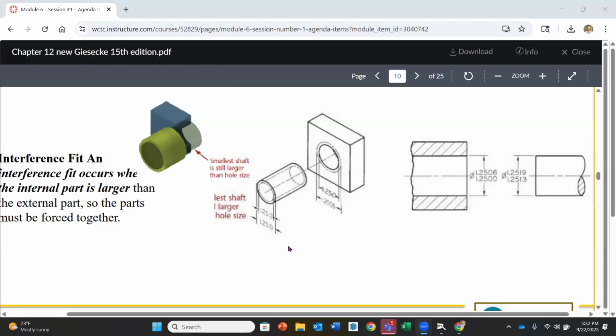So if it's something that's going to be metal on metal and you just want them to stay together, then usually, a couple thousandth is maybe reasonable. But when you're starting to look at precision types of machine elements like bearings, now you have to start. I'll tell you a story about bearings. That was something that we used a lot in high-speed packaging equipment when I was at Hyson, and that was my first job as an engineer. And for bearings, like a ball bearing, we were holding 4, 5, 6 decimal places sometimes. And they were quite critical. So they were considered a precision element that we'd have to deal with.